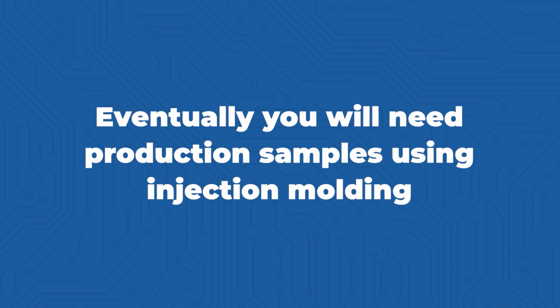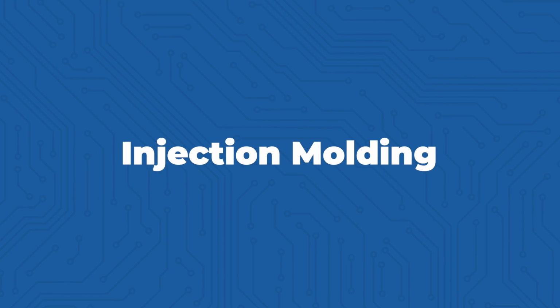And the only way to get exactly production units is to use injection molding. That should be the last step, because injection molding is expensive to have the molds made, and it's the most difficult to change. You don't want to spend thousands of dollars on a mold and then realize that you need to make some changes to it.